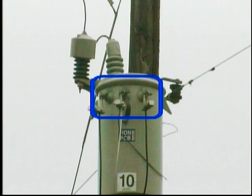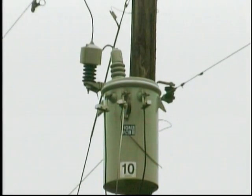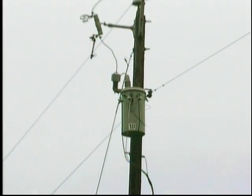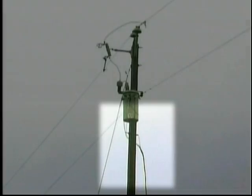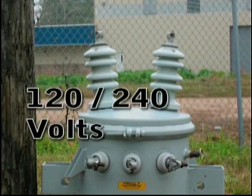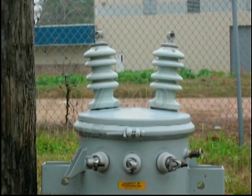Secondary bushings are also located on the side of the transformer housing. The bushings are insulated for secondary voltage and serve as connection points between the secondary winding and the secondary load. Another common transformer design is the single-phase, two-bushing transformer. This unit is also typically rated to provide 120/240 volts to a secondary load.